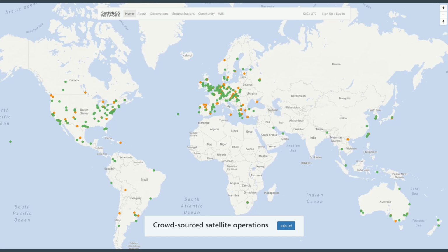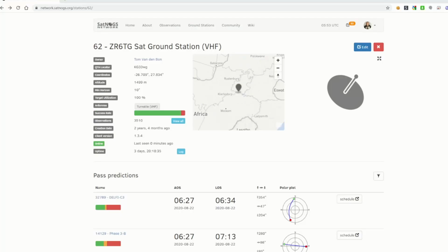Another fun project to do is to learn more to automate the various bits of what we've discussed. This is where I get to chat a bit more about the SatNOGS project. The SatNOGS project essentially is a Raspberry Pi based project which you can put together to automatically track satellites, but also receive and record their transmitted signals. This is great for satellites that only pass your home late at night or at any time that you aren't there to receive the signals.